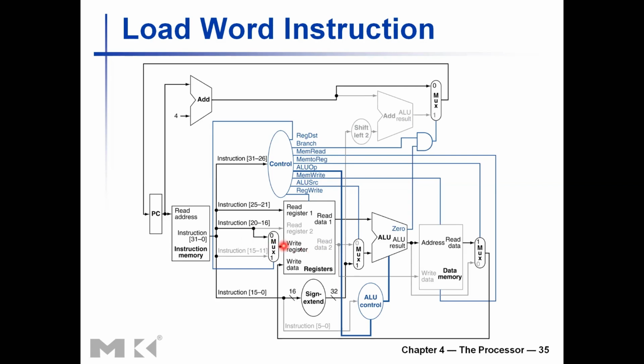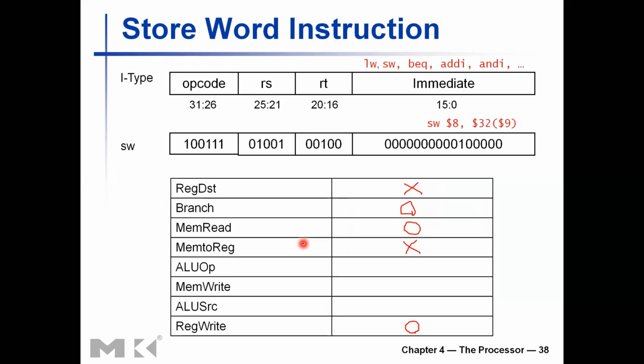Some address will come here because we will be sending either a 0 or 1 along this control signal. We don't care. Some address will go into that port. Some value will go into this data input, either from the data memory or the ALU based on that control signal, because that is also don't care. So if we do not set a 0 here, something will be written to some register and corrupt the value in that register. Make a clear note of that point. We have to send a 0 here, otherwise the data in our register file may be corrupted.